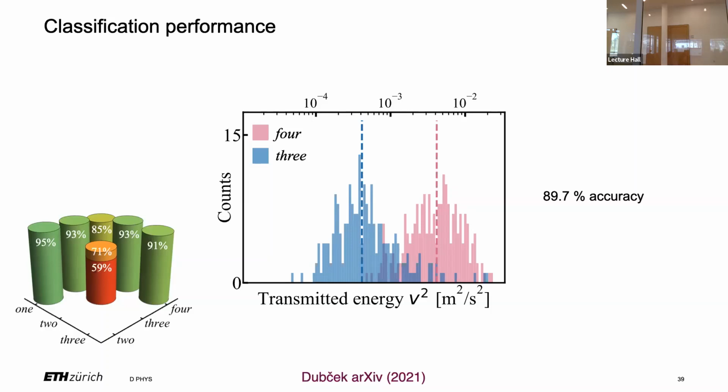So you can multiply the output signal, and with that essentially introduce non-linearities. So in this way we go from here to here. And this is really a proof of principle only, in the sense that all of this only works at, now I forgot what was the carrier frequency here, around 70 kilohertz. We don't speak in 70 kilohertz. So we modulate a 70 kilohertz signal with the 3 and the 4.